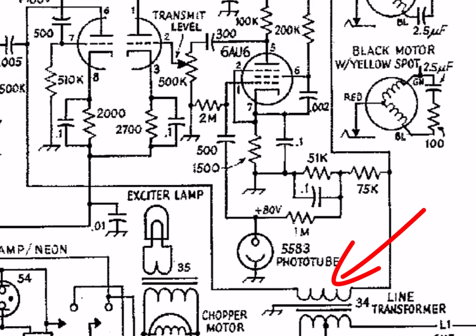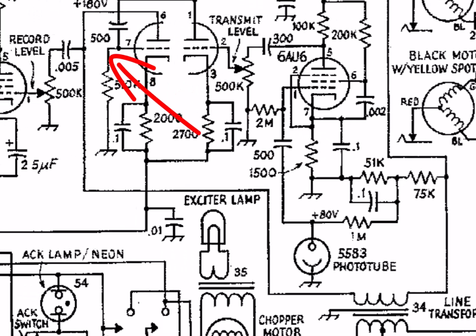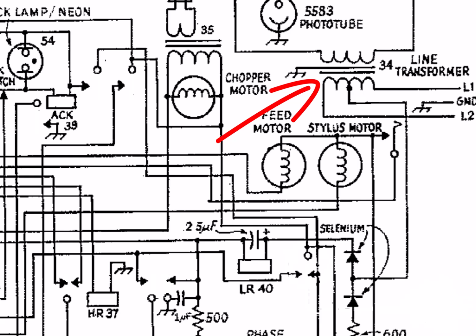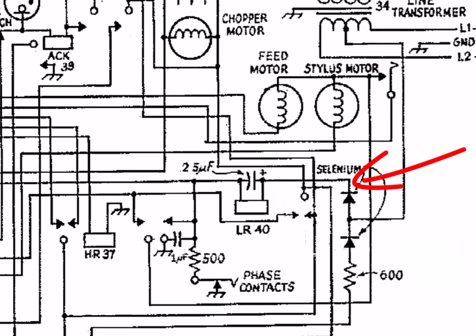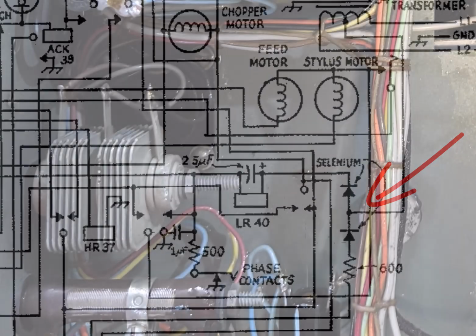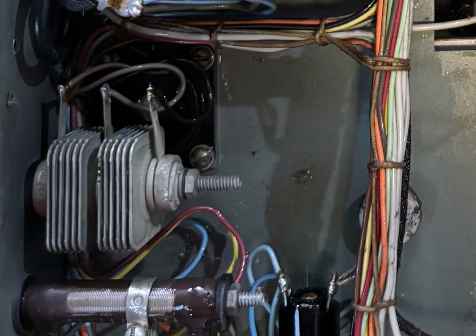Over here on the right is the subscriber line loop transformer. And just as I described earlier, the amplifier winding connects to the 2 amplifiers. The subscriber loop side has the winding for the image data current loop and the center tap for the commands that are coming in as those DC common mode currents. And here's that ground connection that came in with the subscriber loop wires. The center tap comes into these 2 selenium rectifiers. And if you haven't seen a selenium rectifier lately, here they are on the device.